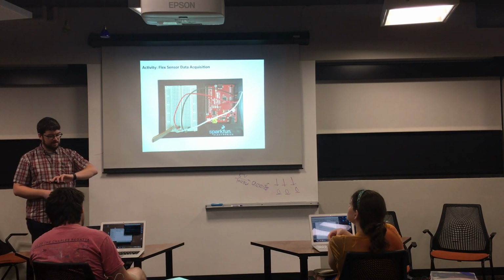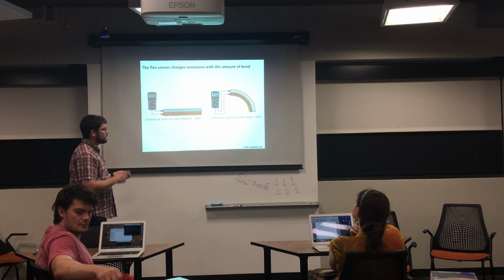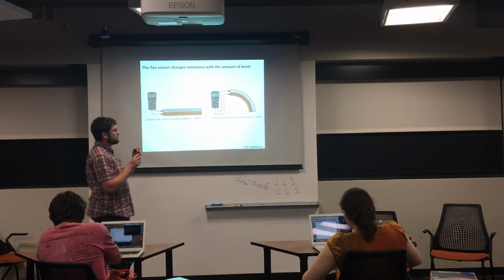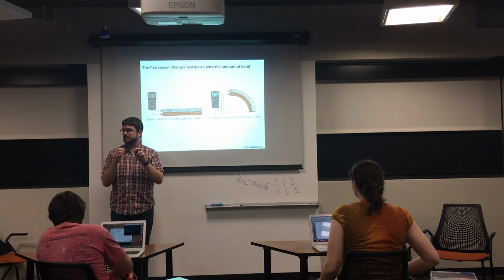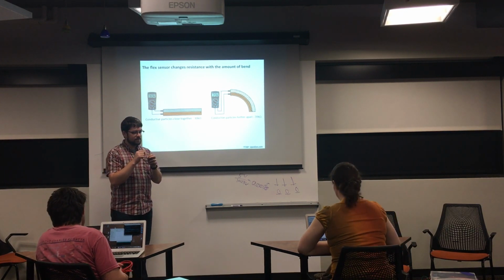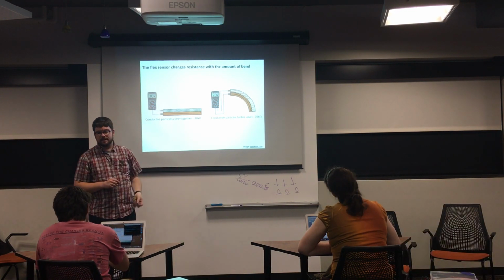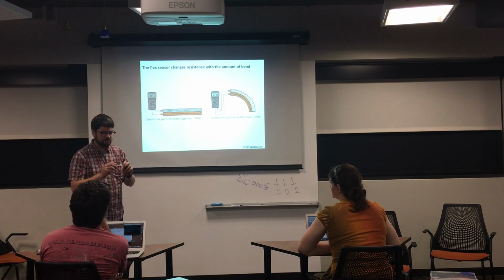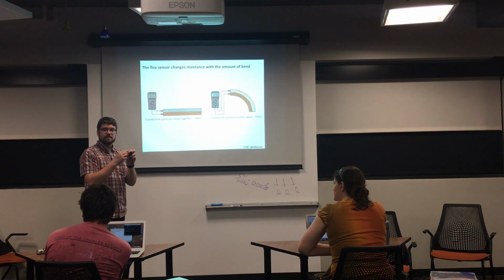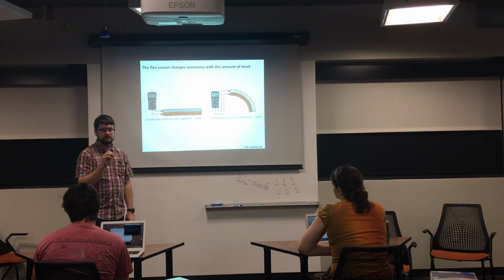All right, so we're going to go back to the activity here in just a second. A few things I want to go over though. So your flex sensor is actually a bunch of conductive particles embedded in the little plastic membrane that's inside. You can see like the little black parts in there. And so when it's like this, its resistance, they say it's 30K. I measured mine, it wasn't quite that. It was something different. And then when you bend it, those particles are now spread further apart, so the resistance goes up. And it actually goes up in a surprisingly linear and nice way.